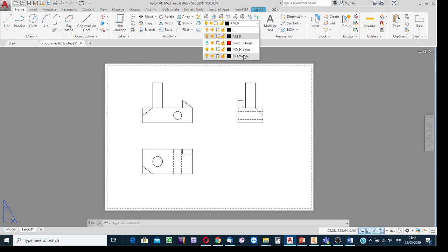In visible layer, AutoCAD created the projections of visible entities. In hidden layer, the images of hidden entities. These dashed lines are just the corresponding views of hidden entity, relative to observer.